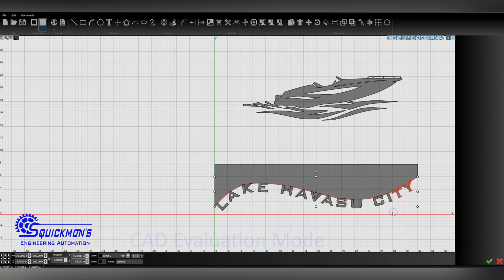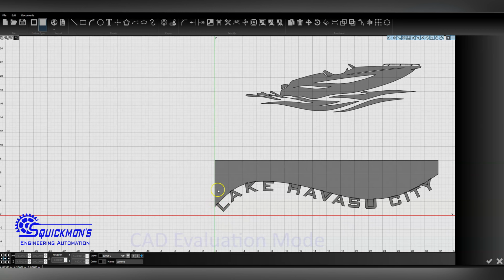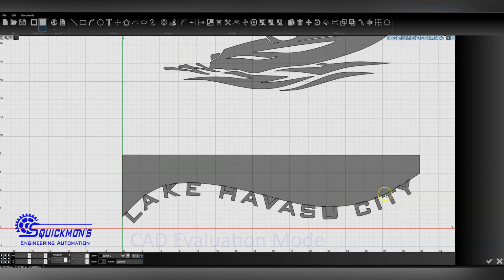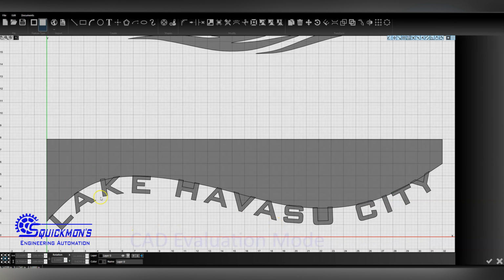So I'm going to want to scroll over the text, and we're going to go from left to right. So let's do this. Control and deselect the arc line. I just want the text. So now with all the text selected, I'm just going to click G, which is group. So now it's all one thing. Select the spline line, outer line, outer line, outer line, and click G. Now put this whole thing together so it's one connected body.